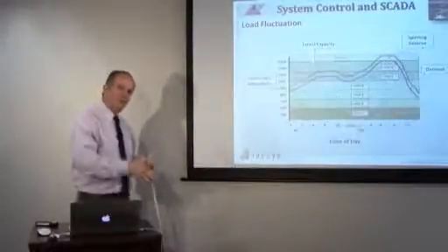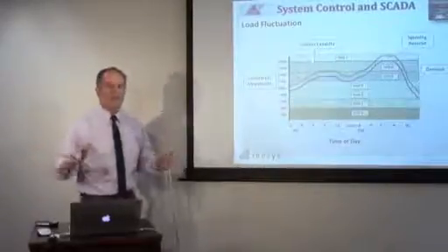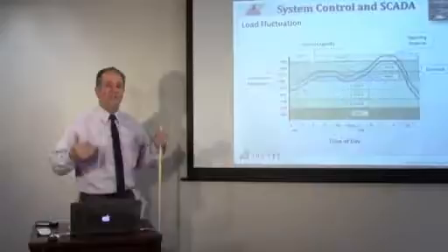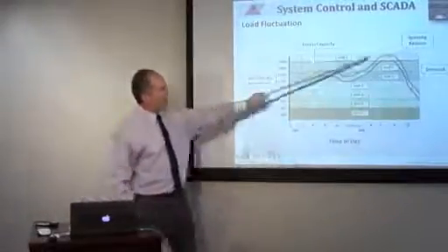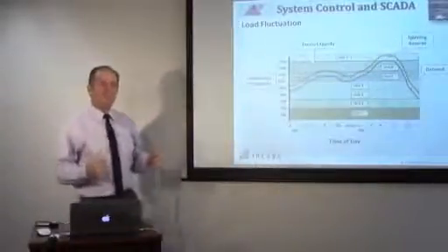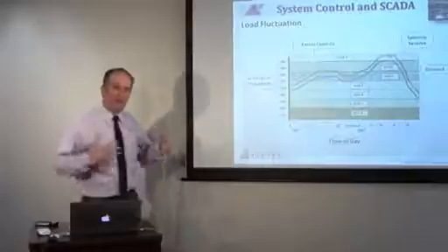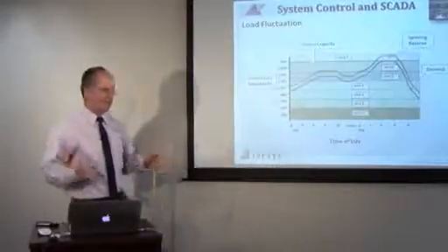If a generator trips off, we want to ramp up the other ones because they're already spinning, they're already online, or they come up to speed very quickly and can be put online quickly. So we have what's referred to as spinning reserve so that we can handle a generator trip and absorb that with the rest of the generation and get right back to a stable frequency again.